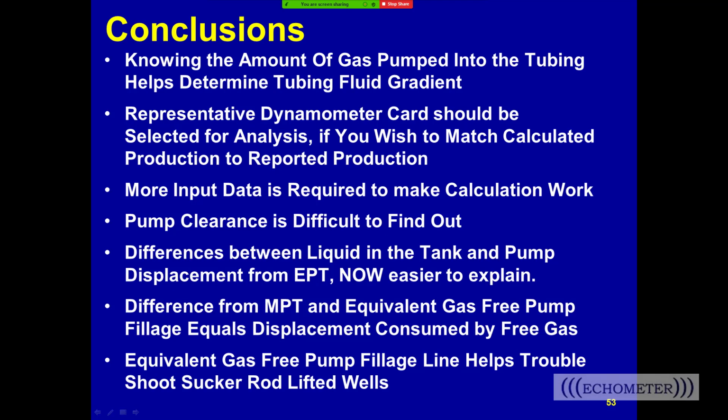You get a big hump to cause the fluid to leave the pump chamber, and then an echo hump, and that's two humps. But most of the time, that just occurs on a very shallow well with a plunger diameter larger than the flow area in the tubing. So the viscous crude just means you need to have a higher damping factor.